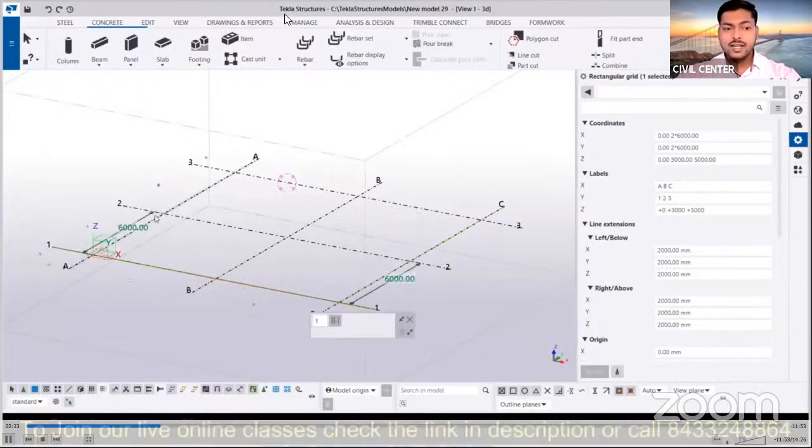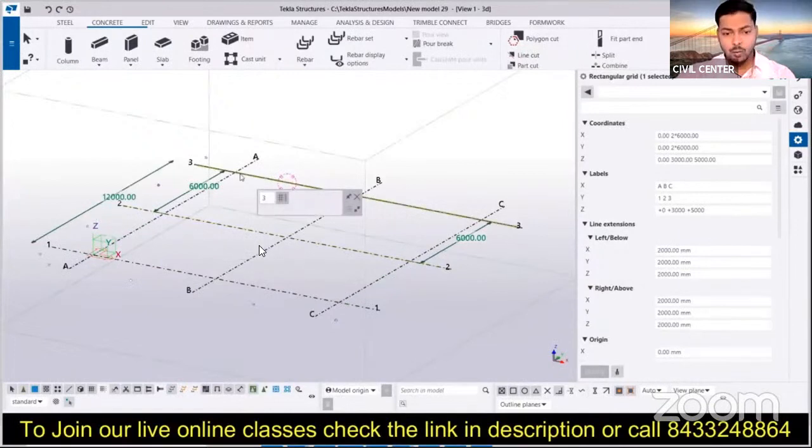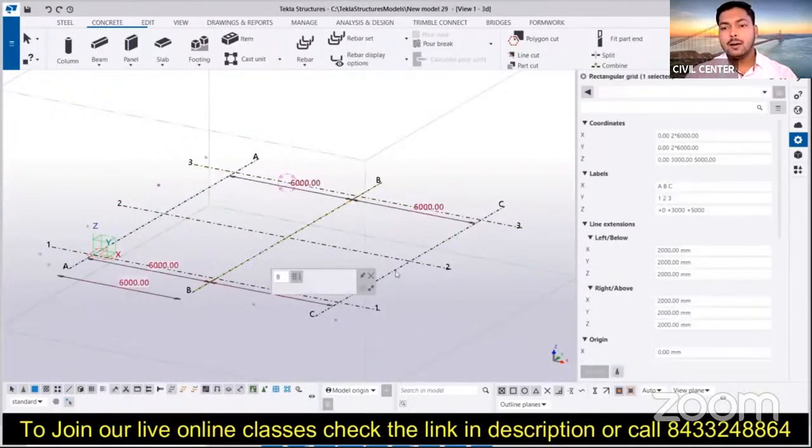You can see this is the interface. On the top we have the title bar, then the menu bar, then the toolbar where you can find a lot of tools, and over here is the grid. These grids can be modified easily according to your requirement. How do you do that? You simply take out the distances of each and every grid. Now let's see how you can change these distances. For that, you have a property box on the right, and here you can change all the distances required by you.